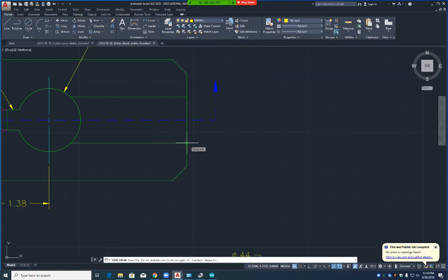So go ahead and stick this one onto your drawing. Don't forget your hash marks. And then you want a center line on the hole in the slot. Right, Mike? You want a center line, center mark in this hole, right? Yes, it has to have this hole.